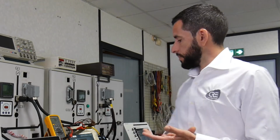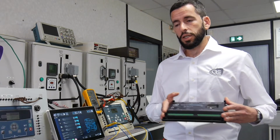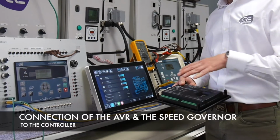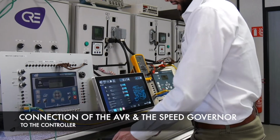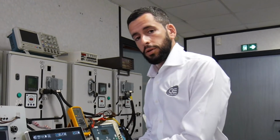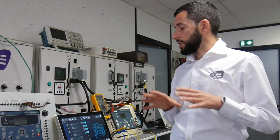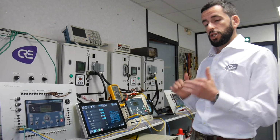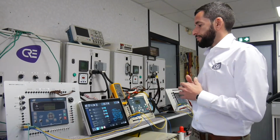So EasyCalib will be set up once this connection between the controller and the speed governor and the AVR is done. Once your genset is correctly set up with frequency and voltage, we can connect the AVR and the speed governor to the controller. It can happen that because of the default settings of the controller, the frequency or the voltage will drop or change from its nominal, but this is normal. EasyCalib is made to start from that and adjust properly to the nominal again.